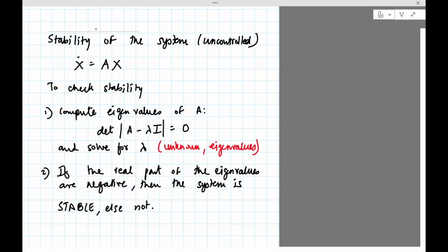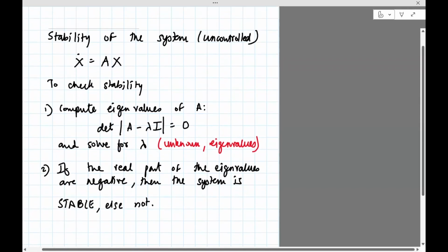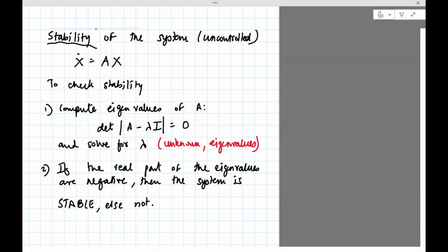It always goes down to the zero position, which is the downward position. If you take the pendulum and invert it, you make it go up. You basically write the equation such that the top position is the nominal position, that is the zero position. And if you try to write the state space form x dot equals Ax, you'll find that the eigenvalues are actually positive, which means that the system is unstable. In fact, an inverted pendulum cannot be stable. It will actually swing in such a way that it will eventually end up in the stable downward position. So that can be shown for a system like a simple pendulum.